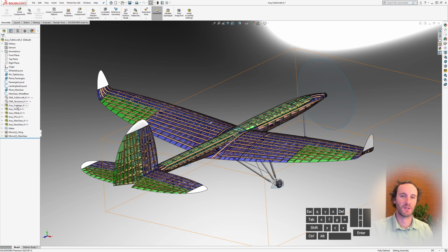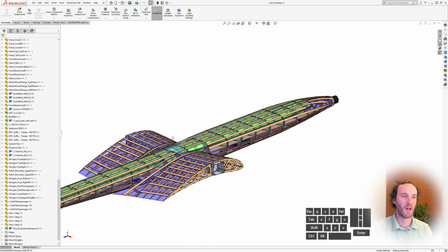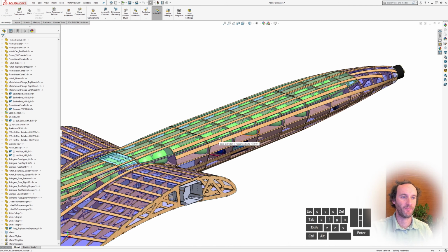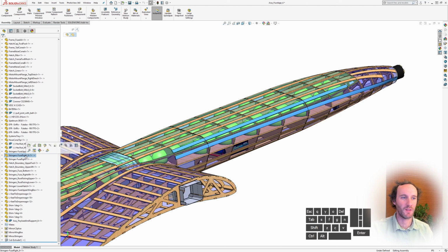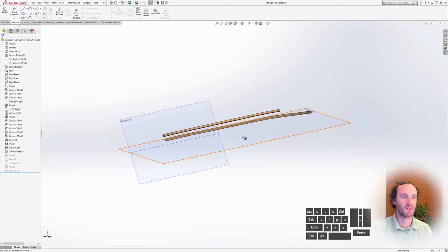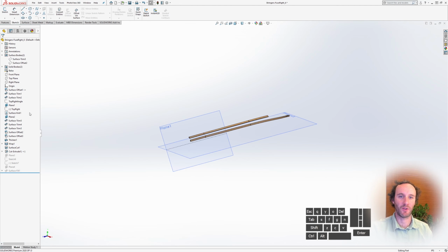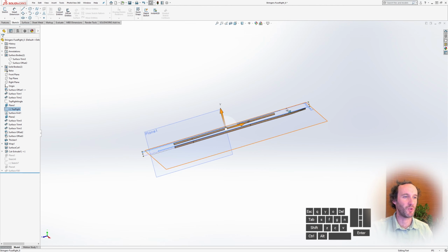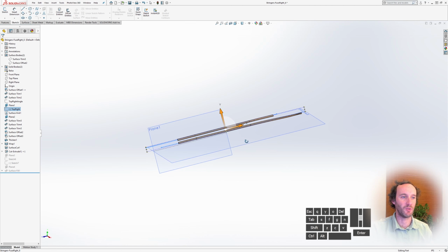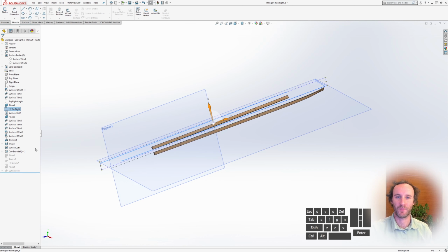Another caveat is that sometimes the wrap can fail to calculate. I find that if that's the case, often you just have to very slightly adjust the layout sketch. You can move the lines even just 1/100th of an inch, and sometimes that can get it to solve.